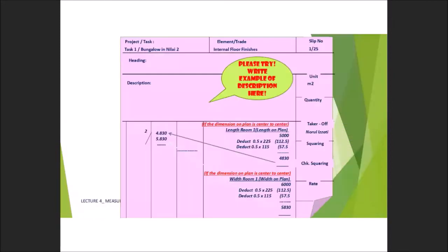Okay, so if you combine with all the rules, you can see the example to write the description. Okay, look at the example given in the recap part. Okay, write down the type, write down the thickness, and how to apply. If you fulfill the example with this category, you can write down your description properly. Material, linoleum, vinyl, okay, and what kind of vinyl flooring, and then after that you have to write down the thickness. Okay, you can see also in some of the suppliers' websites what the common thicknesses are.